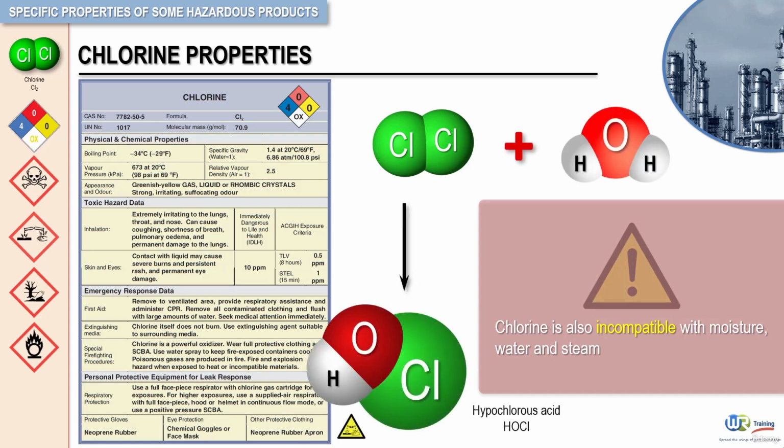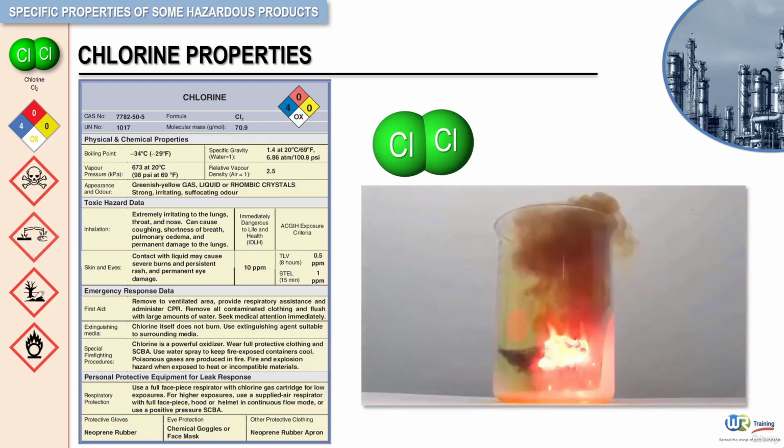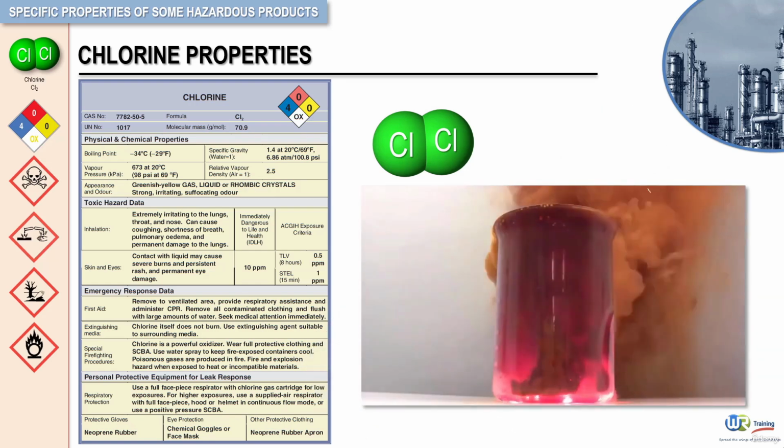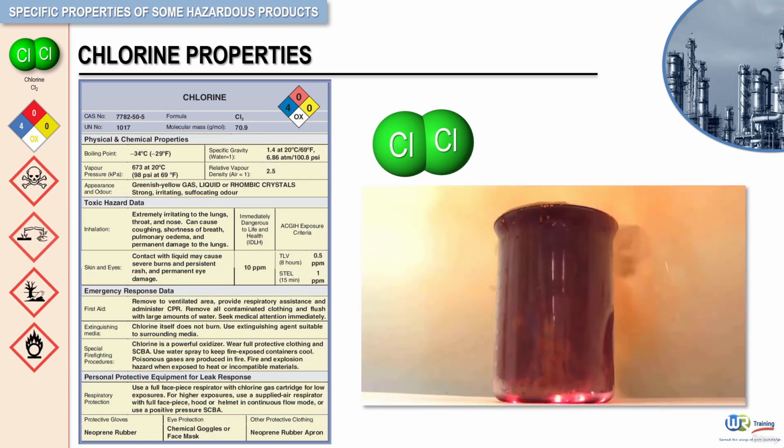At 250 degrees Celsius, chlorine will oxidize steel, essentially burning it. In the next demonstration video, you can see what happens when steel wool is dropped into chlorine gas. Chlorine also reacts with steel at lower temperatures under certain conditions. Oxidation will lead to a fire, which should be avoided since water cannot be used on a chlorine fire.